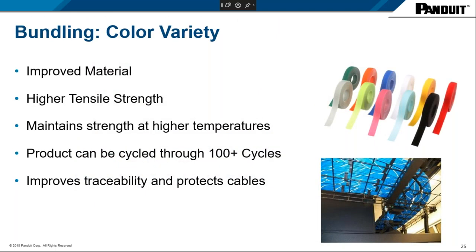And here I wanted to move into, quickly before we end, the importance of bundling. Especially when you're putting product into a wire mesh basket, when there's a lot of cutting involved, you want to make sure that you're bundling the cable. By bundling the cable, you're able to provide pretty much a larger diameter cable there, in the sense that it does provide that protection, and you're also able to maintain it and push it away from any sharp edge or burr.